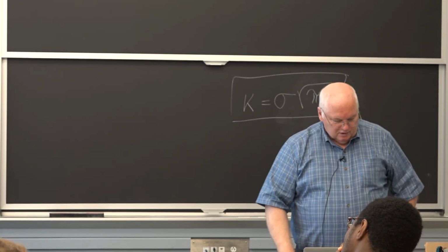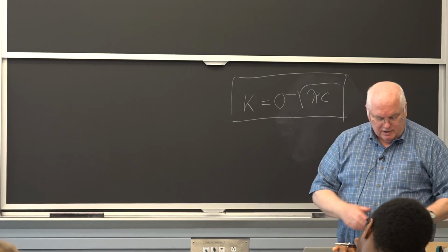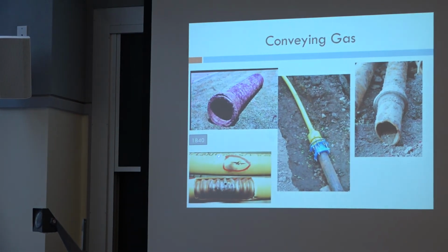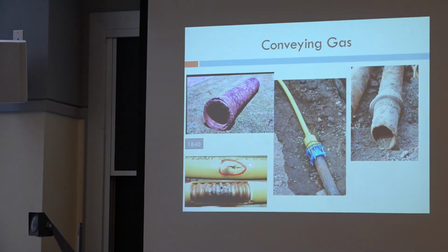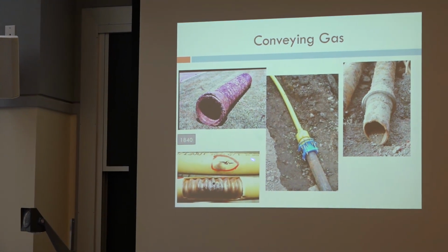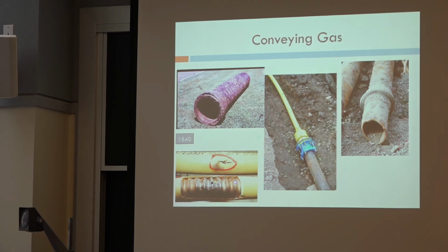So, we use a lot of different materials. This other one down here is corrugated stainless steel tubing. This is another thing that the Gas Association came up with in the 1980s. It wasn't really approved for residential use until 1997. The problem with this is it's got the yellow coating on a corrugated stainless steel, and if you have lightning come through, like if you live in Florida, which is Lightning Alley, Florida has a higher density of lightning strikes than any other place in the world. It's surrounded by water that forms clouds that form lightning, thunder and stuff. You get hit by lightning and you can perforate this, and now you have a flamethrower in your wall and it burns down your house.